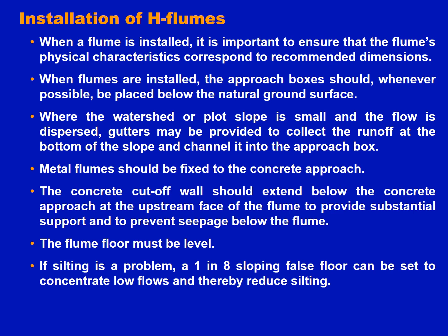Another 3-4 general points are there. The metal flume should be fixed to the concrete approach. The concrete cutoff wall should extend below the concrete approach at the upstream face to provide substantial support and prevent seepage. So this is for the strength or stability of the structure. The flume floor must be level.